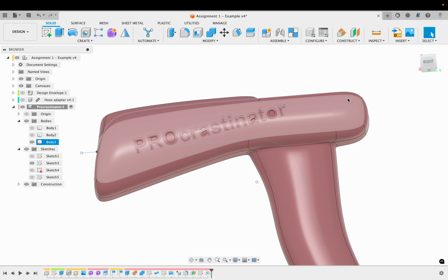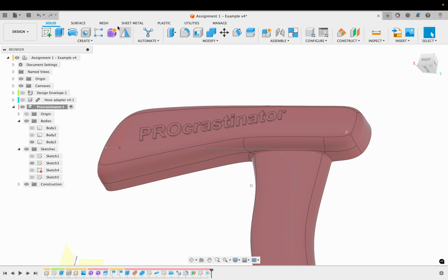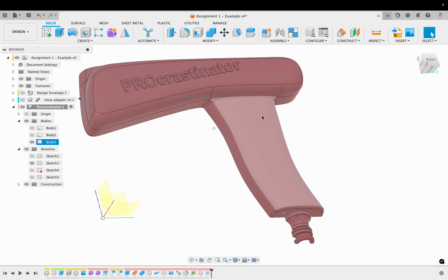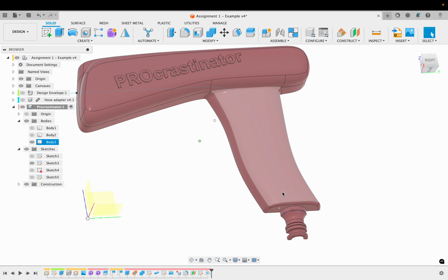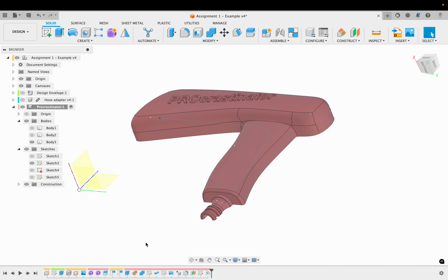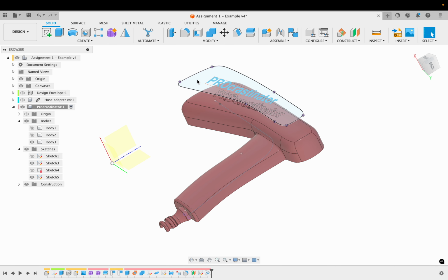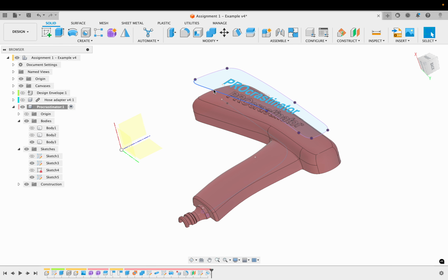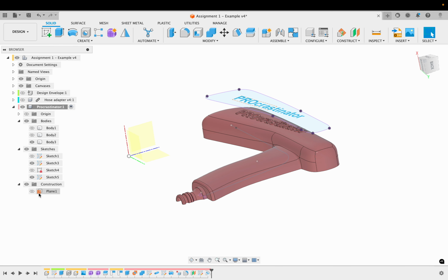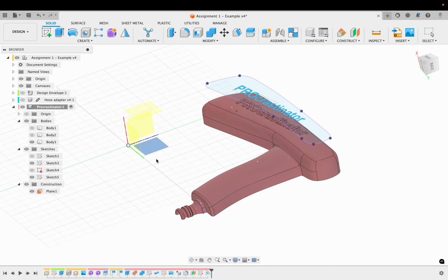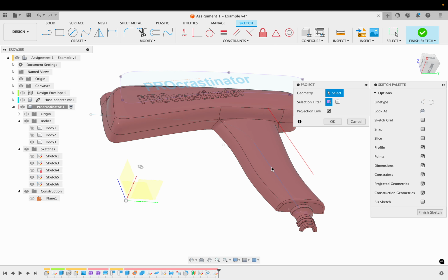Another thing you could do if you want one area with a pattern and you want to play with this geometric pattern thing, you can try and split this face into multiple areas. Maybe I should do that for the handle. Let's say that the handle should have a grip pattern. That would kind of make sense. So I will do the same strategy again. I will make my sketch that's a bit offset, and I will just project that down to the thing itself. So I could just go on with that, but I'm just going to make a new sketch. So construction, that's where my plane goes, and then I'm going to do this, and then I'll select my handle.